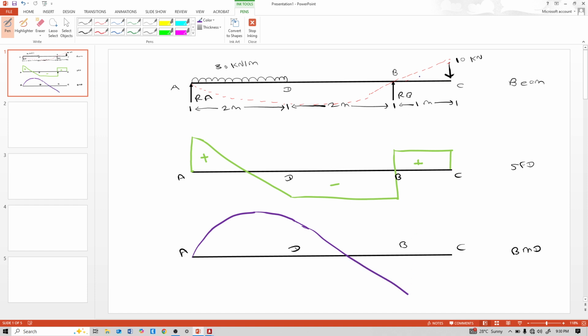And here, see the deflection, that's why a hogging moment occurs. Negative, positive. So see, the point of contraflexure is where the bending moment changes sign. So this is the point of contraflexure. This point P is the point of contraflexure.